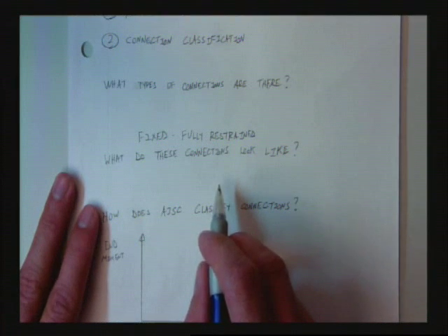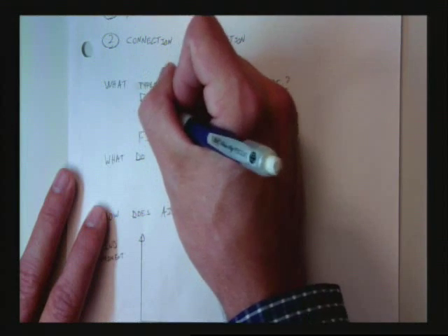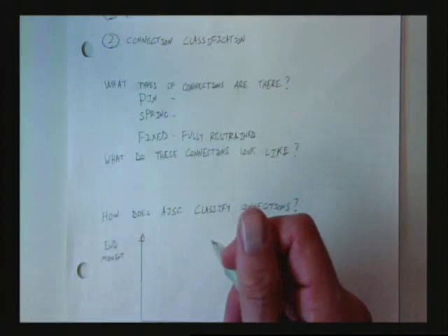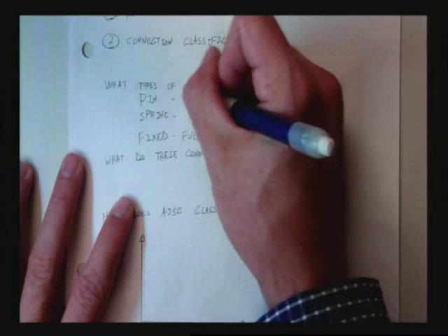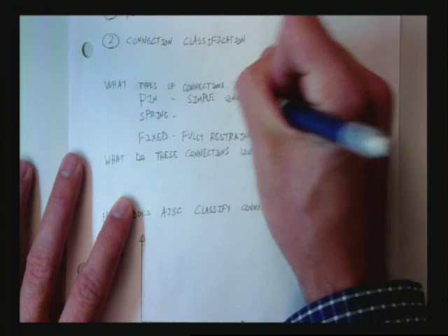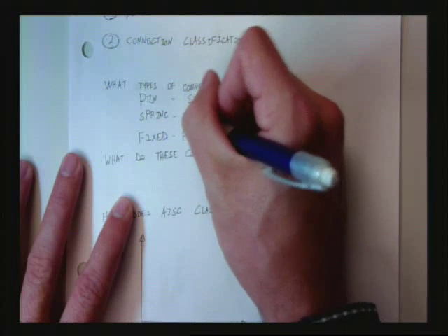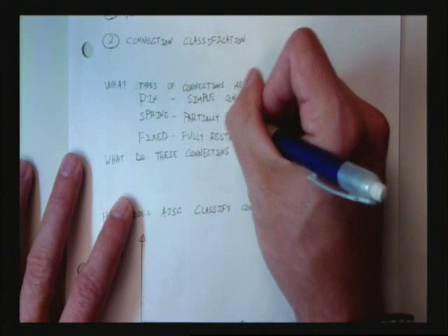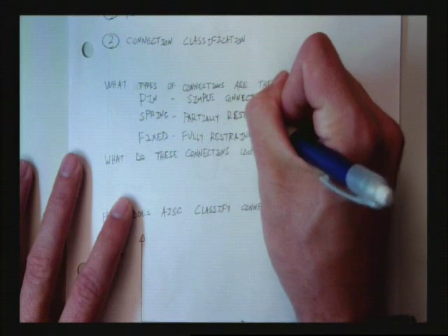A pin, and then you have a spring. A pin and a rotational spring. Very good. And I'm glad you responded that way. That's how I'd respond as well. But if we talk about what AISC uses in maybe a little bit more academic terms, they would call a pin connection a simple connection. And they would call a spring a partially restrained connection. So, you have to be really political. Well, I don't know if you have to, but these terms seem to become very political. People start to use them more and more.